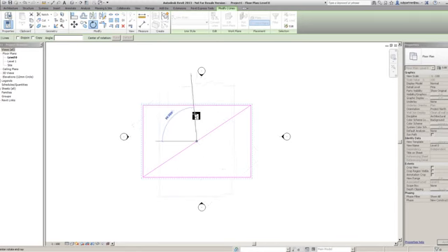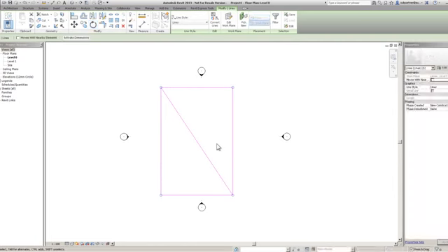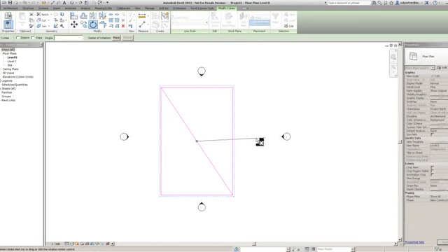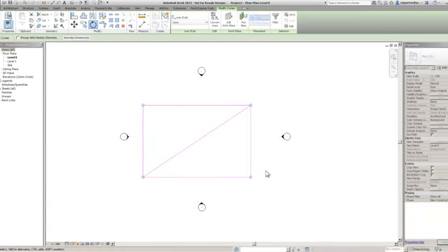You can obviously just input the angle just on the screen just there, okay? Just come around every single degree, okay? But let's just say I'm just going to rotate that 90 degrees up there, left click, done, okay? And again, it's still highlighted, so my modify tools are still up here, okay? So again, I'm going to rotate. This time I'm going to rotate it around, okay? But this time what I'm going to do, I'm going to type in 90, enter, done.